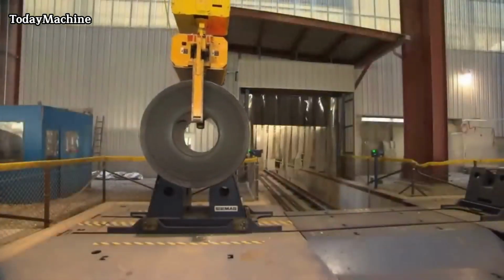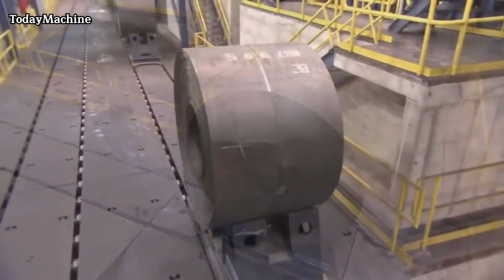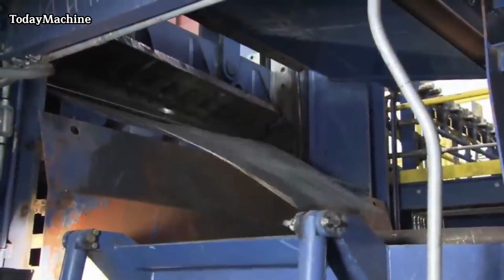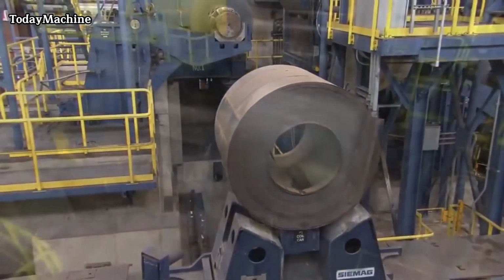As the coils go through the TCM stands, they are subjected to both horizontal and vertical rolling forces. The combination of these forces, along with the controlled tension applied to the coils, allows for precise control over the thickness reduction and dimensional accuracy. In addition to reducing the thickness, the TCM imparts the desired surface finish to the steel coils.